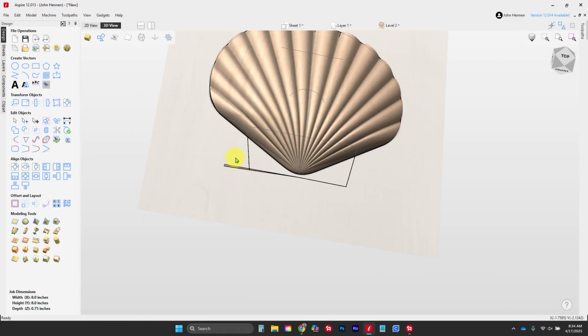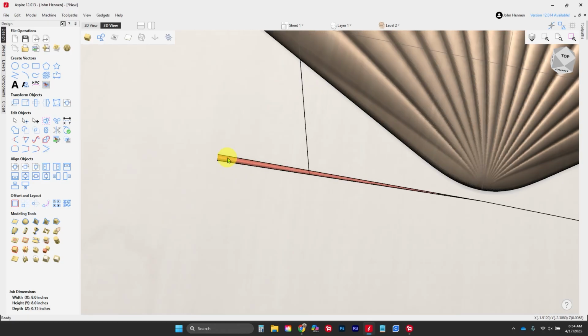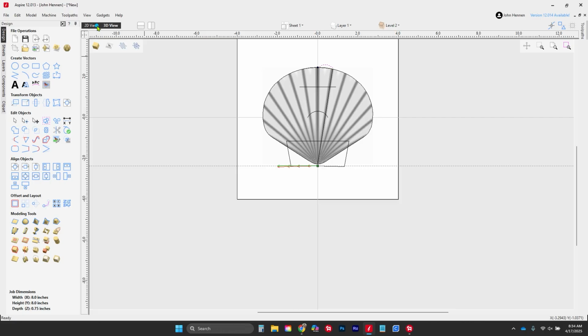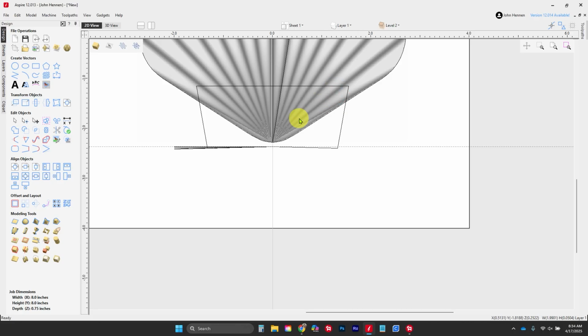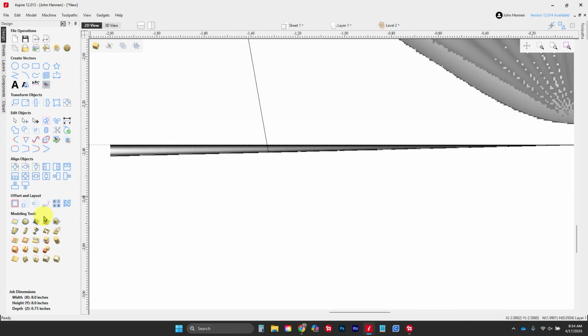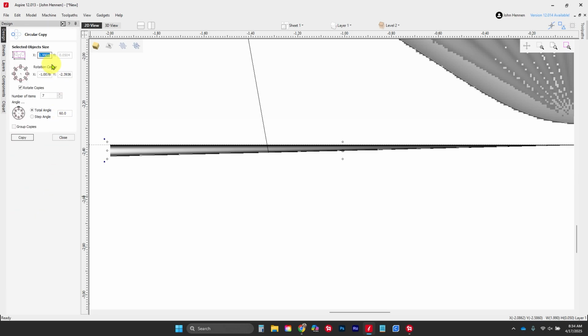Now what we want to do here, we want to make sure that we overlap. Now we can grab it and do some math, or we can just hit go and see what happens. I'm kind of a hit go and see what happens guy. So 2, 3, 6, 9, 7. So let's grab our shape, go to our array, so circular array again, okay, and our rotation center is going to be 0, and 2, 3, 6, 9, 7.